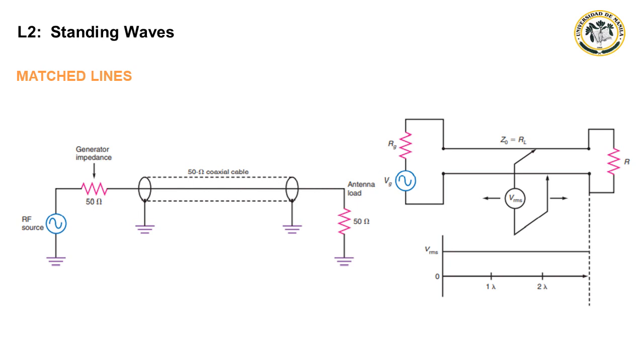The power sent down the line toward the load is called the forward or incident power. The power not absorbed by the load is called the reflected power. The signal actually on a line is simply an algebraic sum of the forward and reflected signals. In cases in which the mismatch between the load resistive impedance and the line impedance is great, the reflected power can be high enough to actually cause damage to the transmitter or the line itself.